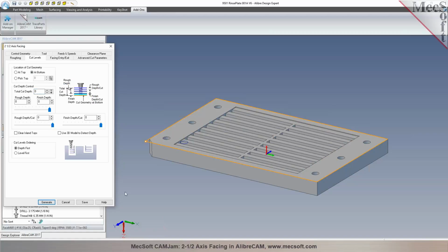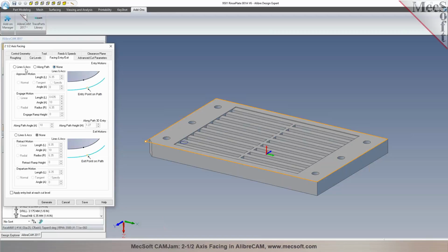it's at bottom. And then the thickness, we know it's 9.525 minus 5 millimeters, like it's 4.525. And you can break this up into one or multiple passes depending on how much you want to take per cut. Got it. Entry and exit, you can specify to have it go past in here. You can extend it. You can specify the same settings for exit as well.